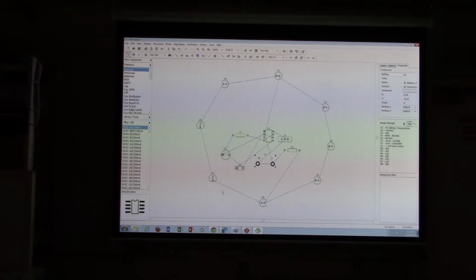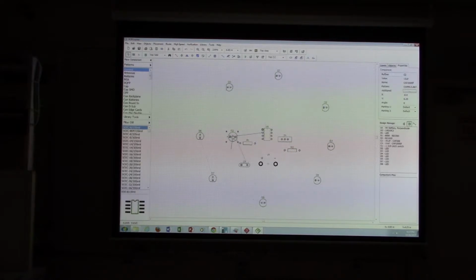Now, this is the general pattern that I want to have for my outline here, or for my diodes. So now I'm going to start working on the actual components. Again, right now these components are in sort of a jumble. No real rhyme or reason to how they're set up. So I'm going to start looking at where all the components are connected, what other things they're connected to, and I'm going to try and move components next to each other that look like they should be next to each other to sort of minimize the number of rat lines that are crossing each other.